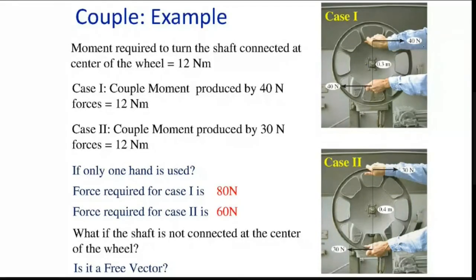The force you apply is 40 Newton. The distance between the two forces is 0.3. So totally 40 into 0.3, you are getting around 12 Newton meter.